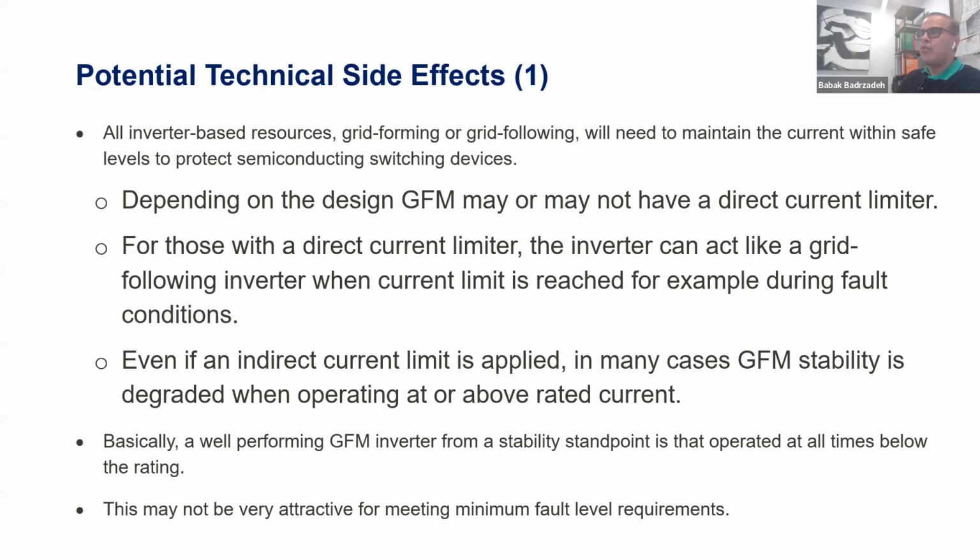And to be most effective, you will still need to have that at the fastest control loop. Which means that you really need to have it in the current control, because if you were to put it at the left-hand side, it's going to be slower and much less effective.